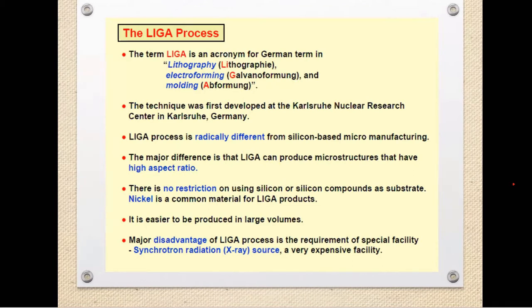We also have a limitation with the thickness of the silicon based substrate. In this method we don't have these types of limitations. And we are able to fabricate non-silicon based microstructures also. As per the requirement, we are able to produce thick microstructures also.